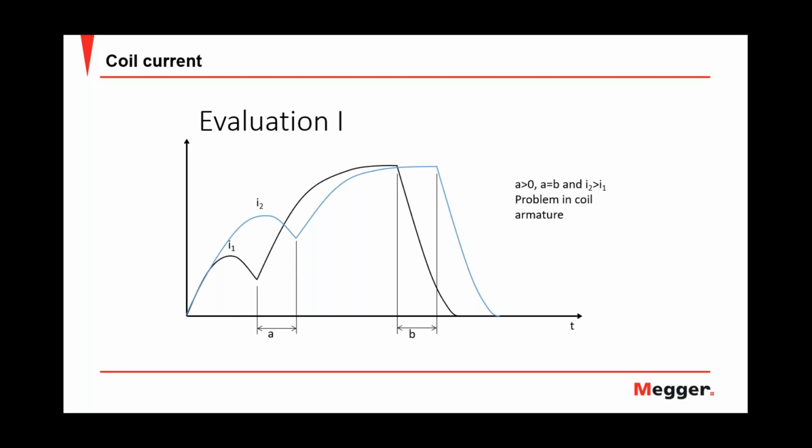So I would say, besides failure due to old age or any other stress, the main source is failure of the circuit breaker to operate when a closing or opening operation was needed, because that will lead to an increase in the time the coil is energized, and the trip coils are not designed to operate for a very long time.